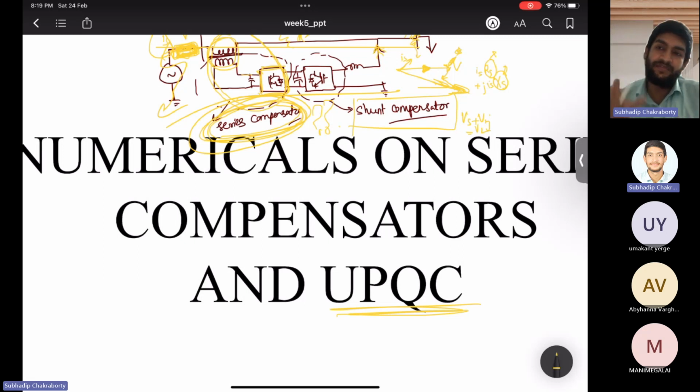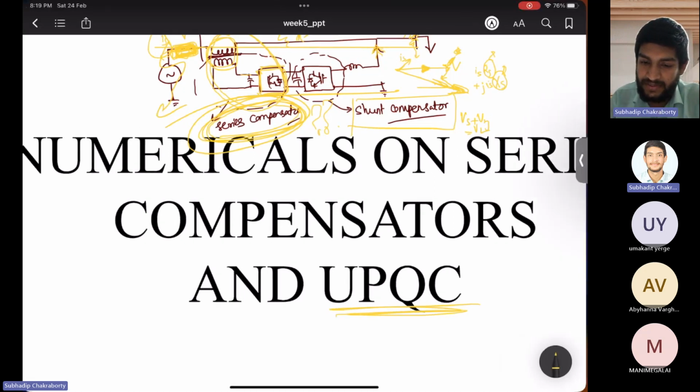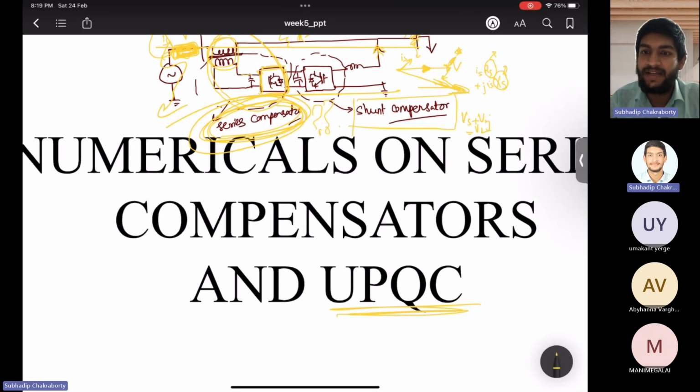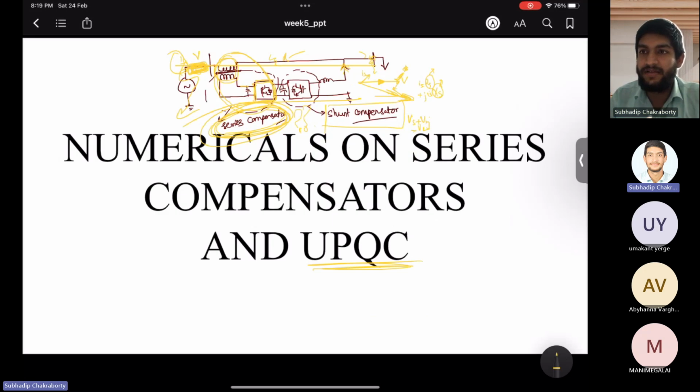So at the supply side I can improve my current quality, and at the load side I can improve my voltage quality, irrespective of the supply voltage abnormality and the load current irregularity. That's why UPQC is very popular.